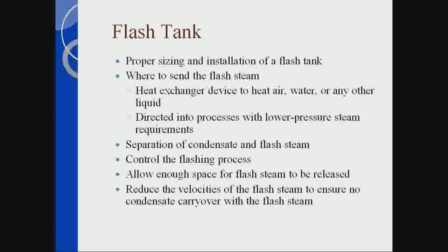In the calculations for a flash tank, you need to allow enough space for the flash to occur, and there are certain calculations that we go through to do that. The other thing is to reduce the velocity of flash steam to ensure no condensate carryover with the flash. We have to make sure that the flash does not carry any condensate with it or reduce the steam quality to the process. And this all comes into the calculation process.